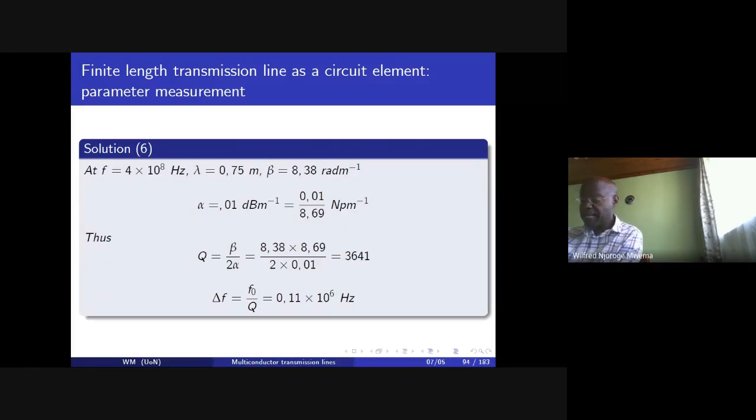You can assume that L prime and R prime now stand for the lumped element resistance and inductance. The inductor is given as 1 microhenry. So you want to get the value of R for that inductor, for you to get the same Q of 3641.